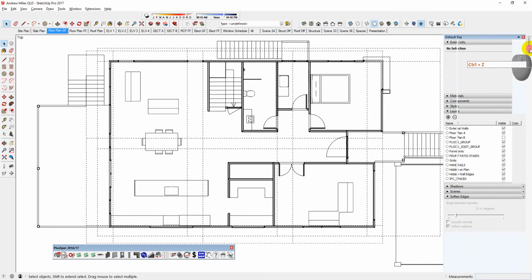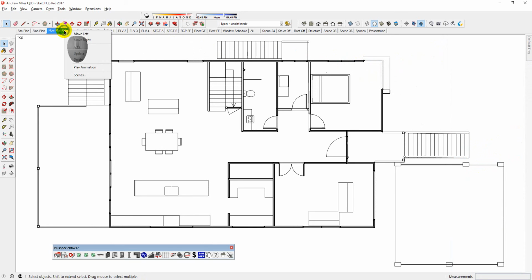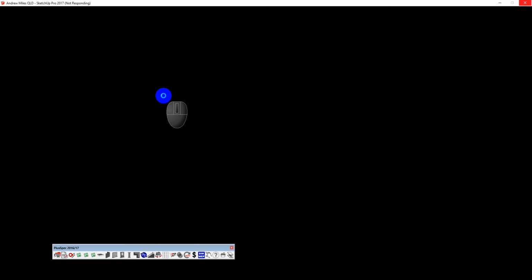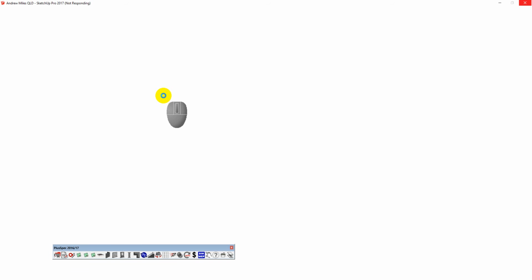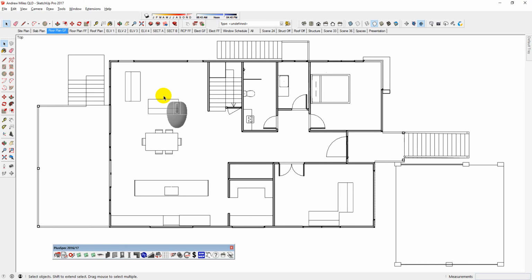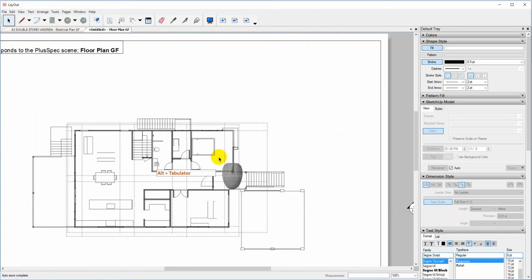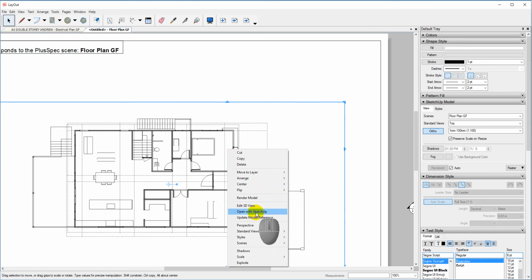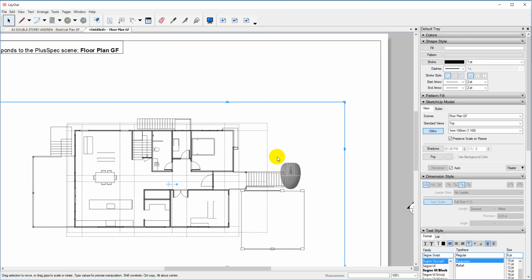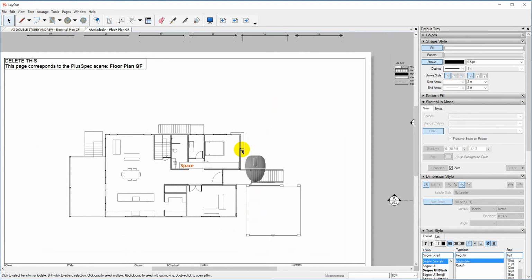Right, and I'm going to turn my grids off. Layers, grids. There we go. I'm going to right click and I'm going to update my scene. Okay. File, save. Alt Tab will take me back to layout. I'm going to wait till it's finished saving first. Okay, Alt Tab, take me to layout, update model reference. Okay, and now I have my grid lines gone.